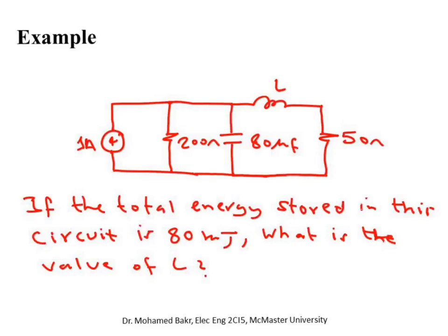And as I mentioned earlier, a capacitor will represent an open circuit, because if the current is not changing with time... let me show you where the origin of this is. We said before that for a capacitor, I is equal to C dV/dt. So if the voltage does not change with time, then this term is zero. It's DC, this term is zero. If this term is zero, there is no current going through it, because I is zero. I is zero means that this is an open circuit.